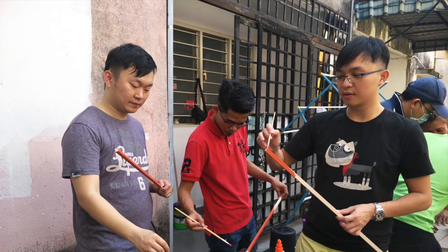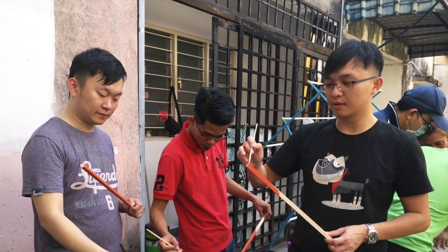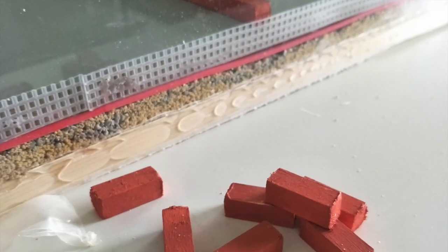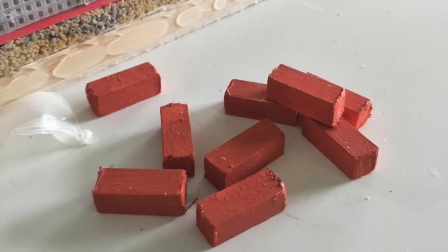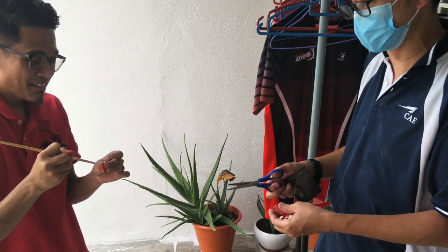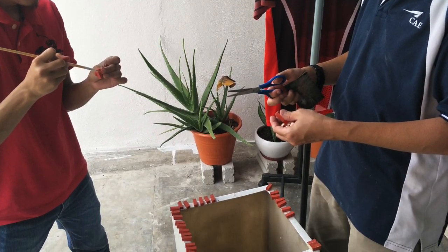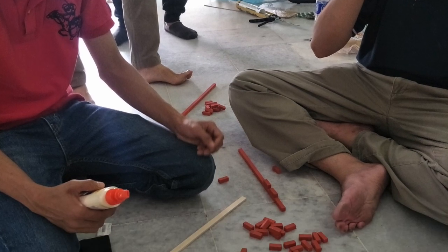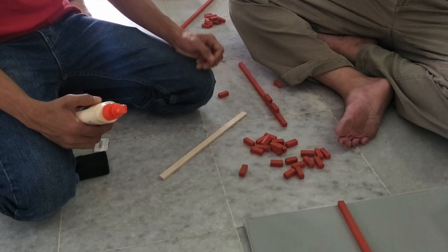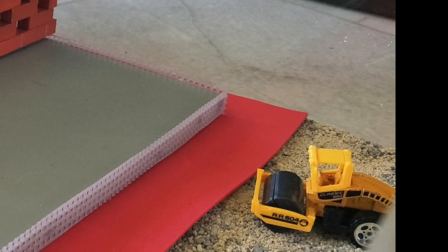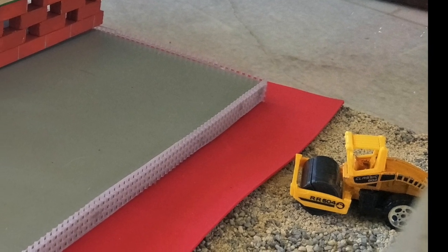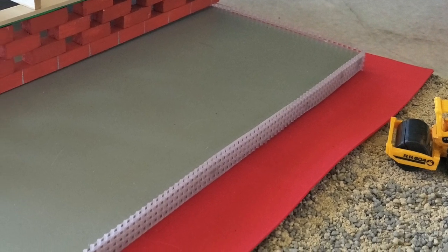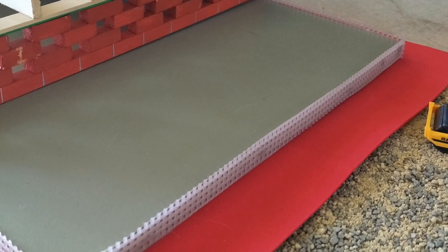The height of the slipper wall and the external vent cannot be lesser than 150 millimeter from the ground. However, there is no specific requirement as to the gap between the bricks for the honeycomb slipper wall. On the working model, we are using basswood strip. We painted the basswood strip in red, similar color to bricks. Then we cut the basswood strip into small pieces and we glued it back with spacing in order to achieve the honeycomb design.